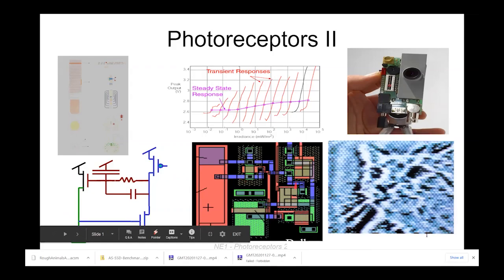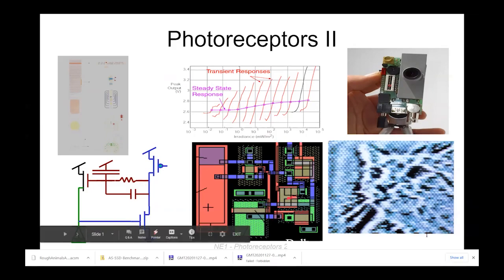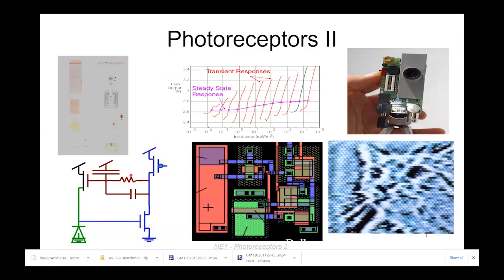And then the amplifier is these three transistors here. It's actually three of them because it's not two like this blue circuit here. It's three because there's a cascode here, a long cascode transistor. The green is the source drain or thin oxide region. And you see how it goes around like this? It snakes around, makes a really long cascode transistor. And then that feeds back through this resistor-like thing, which is a pseudo resistor. It's kind of a transistor arranged to be a very high resistance element.